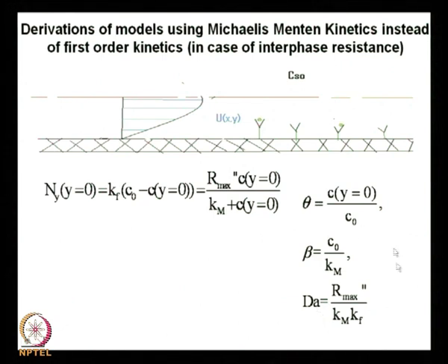And the Damkohler number over here, and you have to be careful with this, is defined using R max. The double prime here signifies this is a surface reaction. It has nothing to do with derivatives. Typically, Rs or R double prime is used for surface reactions, and Rv or R triple prime is used for volumetric reactions. So, again, nothing to do with derivatives over here.